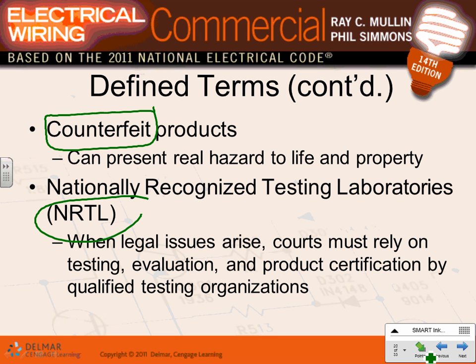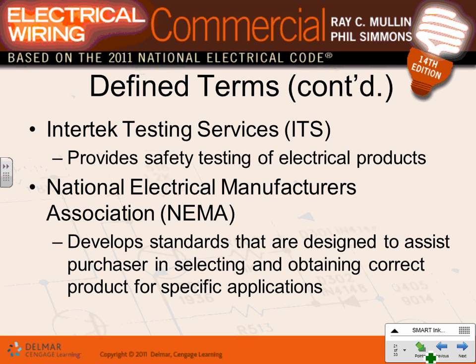And in the electrical industry, UL does a lot of other stuff, guys. If there are any legal issues, a UL-listed piece of equipment at least gives you a chance of winning a case. If you burn a switchgear and it doesn't have a UL label on it or any third-party verification, do you think you're going to win the case? You're not going to win a case from the get-go, even if you follow the NEC code book.